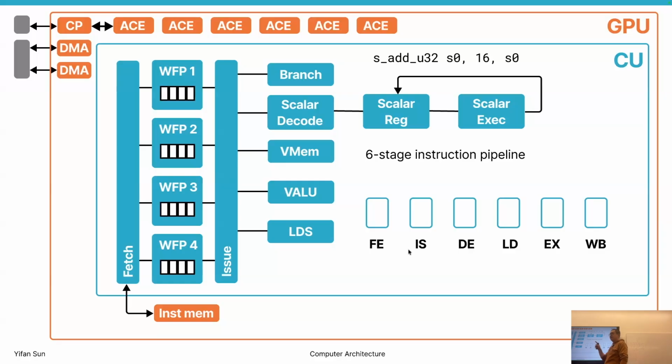That will never happen, because write back for the same wavefront always happens at least 1 cycle before issuing. So then the load stage and write back stage must be filled with different wavefronts. The different wavefronts do not communicate, so they're okay.